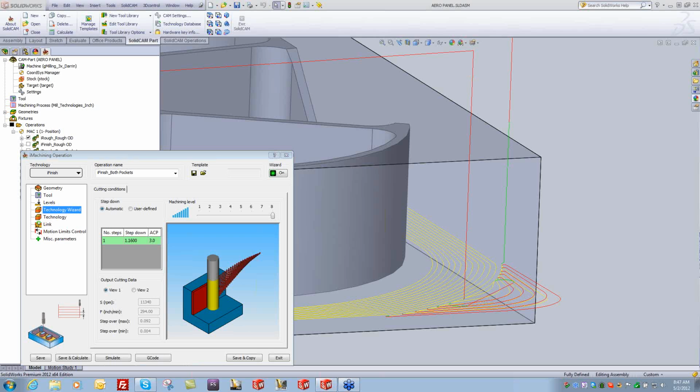Okay. Can iMachining be used this way? We machine turbine wheels with exotic blade surfaces. Seems to be for swarf cutting at full depth. 3 places that iMachining shine, and we can do it in 3D as well. The next release is going to have 3D iMachining. We can also wrap this iMachining around a 4th axis, so you can actually do this. I've done that. It works very well.